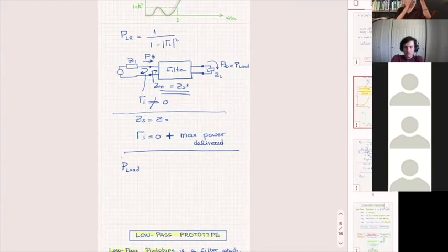You want from your antenna, which is your source, to go directly and have the maximum power go into your filter. So conjugate matching is always very important, unless you have an antenna that provides you with a real input impedance, all right? And then, after that, I'm looking at developing a filter that sends the maximum power down to the load. So that's my important parameter.